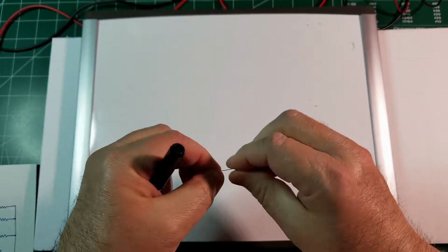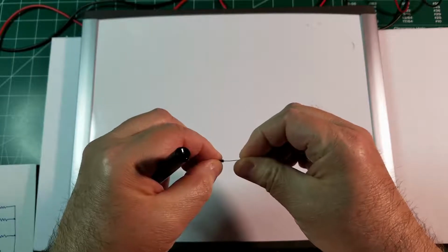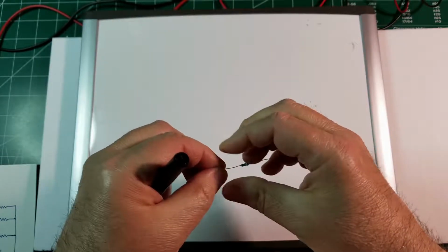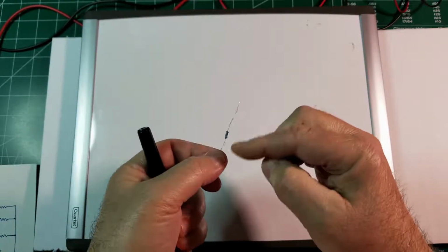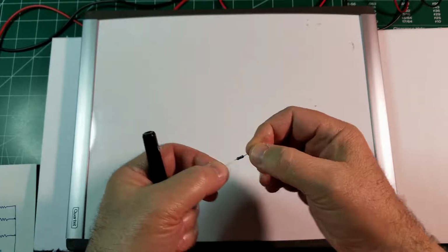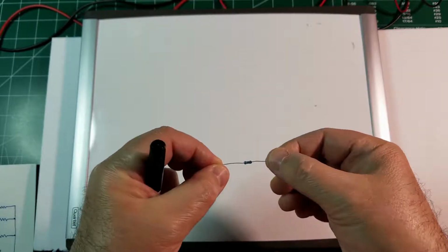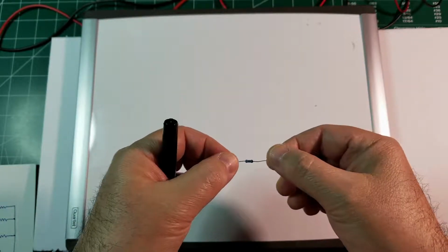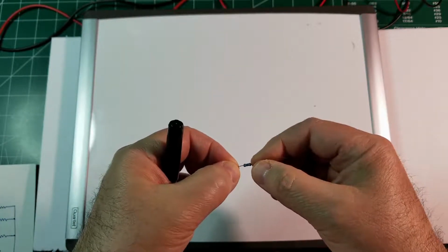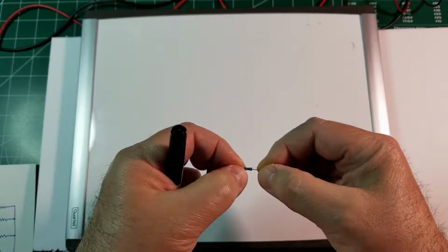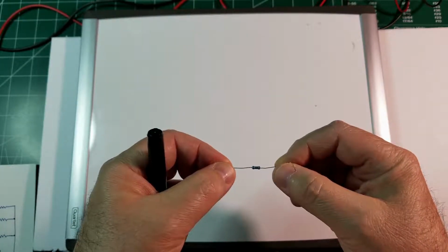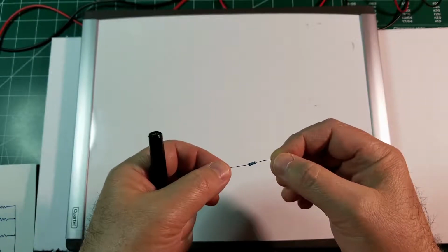Now, the voltage cannot exceed certain values, because otherwise the resistor would break because of too much electric field in between the two ends. However, even for resistors so small, which this is basically 1/8 of a watt in terms of power, the rating in terms of voltage for resistors like this is around 200, 300 volts, something like that.